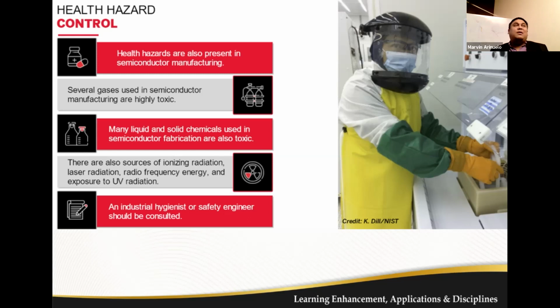I've also had a project in a clean room, and there are chemical pipes going to the equipment in a semiconductor area. In the trench, if there is a leak, we install a leak detection system. It will trigger an alarm if there is a spillage or leakage of the chemical. But when we install the chemical pipe going to the equipment, it is double containment. If there's a leak on the pipe, it will still not leak, because there is another containment.